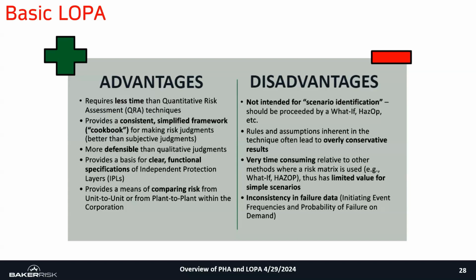LOPA is more defensible than qualitative judgments. And LOPA provides a basis for clear and functional specifications for IPLs. So, how robust does your protection layer need to be? And it also provides a way to compare risk in your facility or across your facilities.